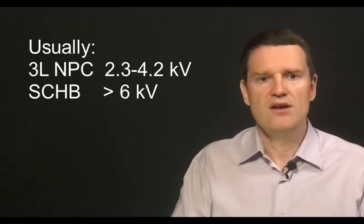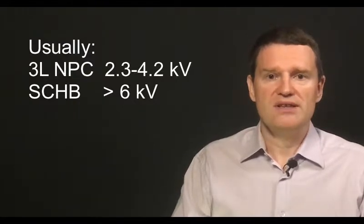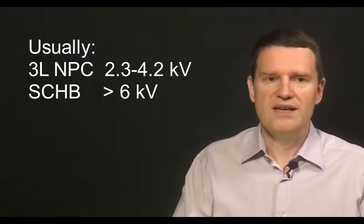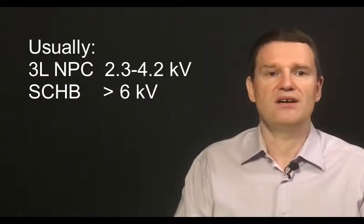The only thing of interest for us in each system is a motor, the electric machine. I mean, we'll be building different systems so that the machine voltage is at the level we need. One of the non-obvious things here is the type of frequency converter. The matter is, for example, 3-level neutral point clamp converters are usually used for 2, 3 or 4 kV, while series connected H-bridge converters for 6 kV and higher.